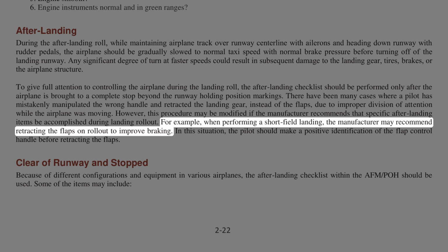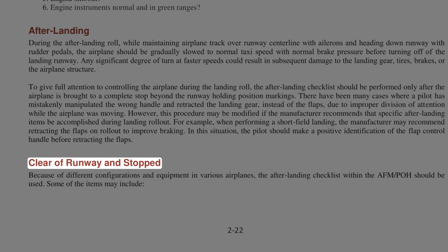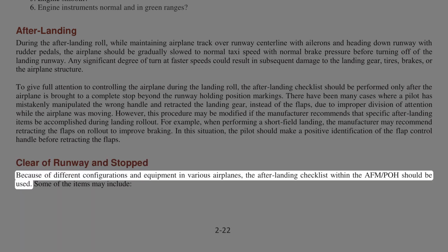For example, when performing a short field landing, the manufacturer may recommend retracting the flaps on rollout to improve braking. In this situation, the pilot should make a positive identification of the flap control handle before retracting the flaps. Clear of runway and stopped. Because of different configurations and equipment in various airplanes, the after-landing checklist within the AFM/POH should be used.